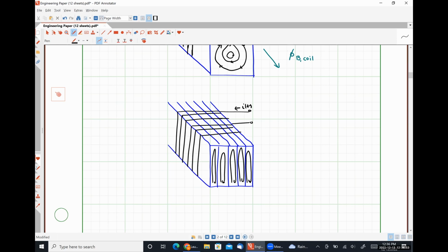One thing that I want to talk about here before we work an example problem is that this practice effectively reduces the cross-sectional area of the core, because not all of the core is made out of magnetic material now. It's some slightly smaller amount. So we might see what's called a stacking fraction of something like 90% or 95%, and all that means is 90 or 95% of the core is magnetic material. The remainder is the insulator material. Okay. All right, so mathematically, everything worked out okay.